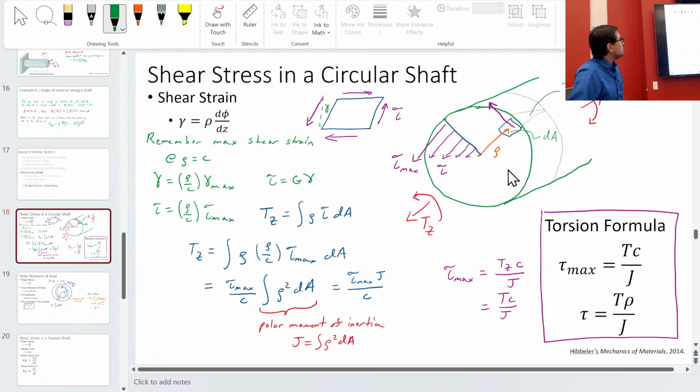So what is going on? We have shear strain, wonderful. Here is another important one: tau equals G gamma. We've already been drawing normal stresses on elements. The shear stress is what causes shear strain, or shear strain often is a result of shear stress, at least for those cases where we have pure shear, and there's no temperature business going on here. So we have shear stress, and this is positively defined. They meet in the bottom left, they meet in the top right, and so on.